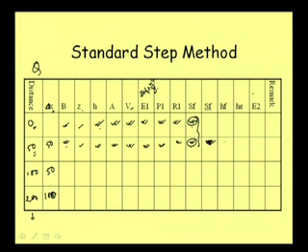Okay. Then we can calculate the friction loss. Once we get the SF bar, then we can calculate the friction loss, SF bar into delta x. Then once we know the V1 and V2, here this is our V1 and this is our V2, taking that V1 and V2, we can calculate the energy loss.